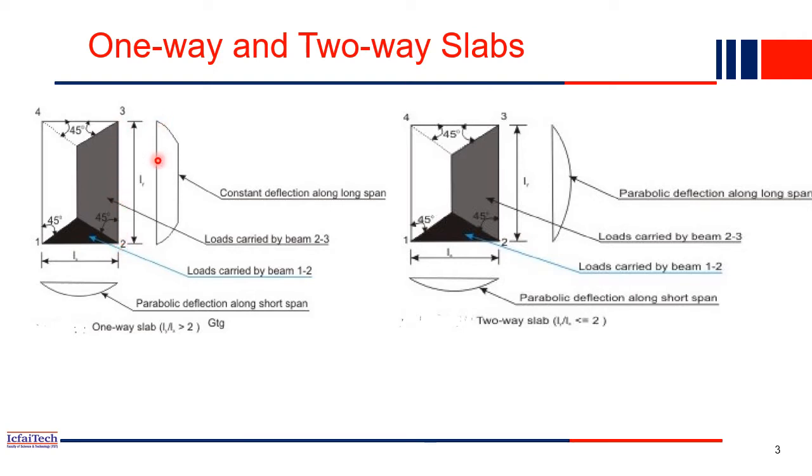That's why, if you see the deformation along the y-axis, it will be something like that. It is constant from the center to here. At the maximum portion it is flat, and you will see constant deformation. Whereas at the edge, you will see the deformation is maybe a little less, because at the edge the loads are comparatively less.